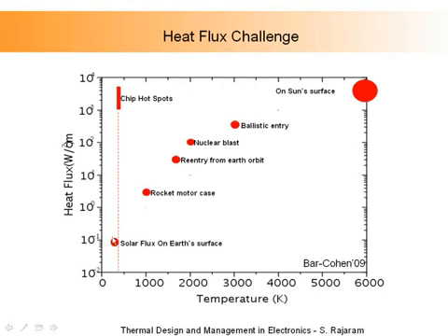For instance, on a bright day, let's say in Bangalore, where you have solar heating, typically around the equator, southern part of India, the solar heat flux is roughly 0.7 to 1 kilowatts per meter squared, 700 to 1000 watts per meter squared. So now if you put a metal plate sitting there to equilibrate, typically you will find that may reach anywhere in the range of about 70 to 100 degrees C. That's like, in the range of 350 to 400 K.